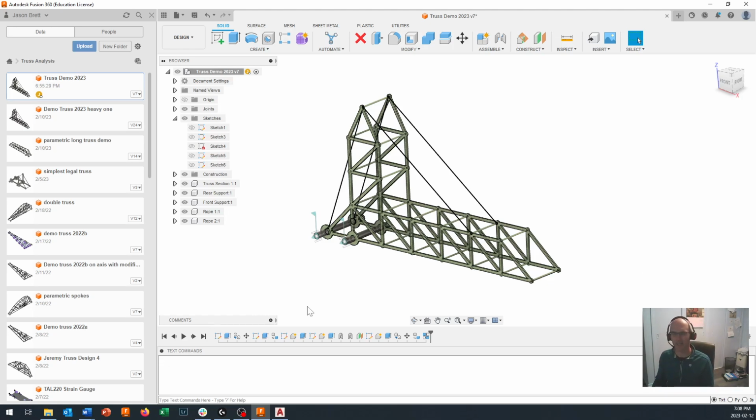Okay, right now, your assignment is to take your design from AutoCAD, import it as a DXF, extrude, copy, extrude your members that come across, and run a simulation to see if your truss is going to stand.